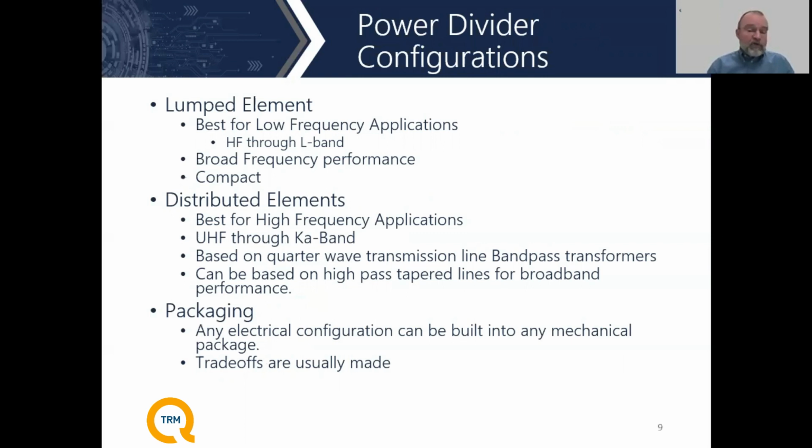That can be built for virtually any power level and any mechanical configuration. Once the power level starts to get higher, though, you can no longer have these as surface mount devices. Then we have to go into a larger package. The cooling of these devices at higher power also tends to be through air. So usually you have to have good airflow once you get to higher power, which usually means for very high power levels, there are cooling fans and things like that that need to be implemented.